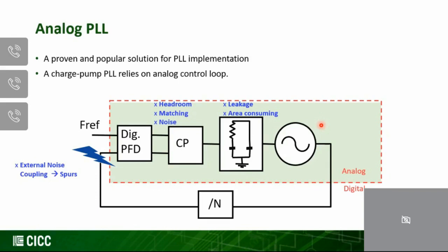Therefore, typically for a phase lock loop, we have to put these free-running oscillators inside a negative feedback loop. As we can see here, a typical feedback loop involves some frequency dividers, where we divide down the oscillator output to a lower frequency, and then we compare this divided down frequency with the clean reference input clock. By comparing these two clocks, we can compare their frequency difference and phase difference, and we turn that into some control voltage to control the oscillator.